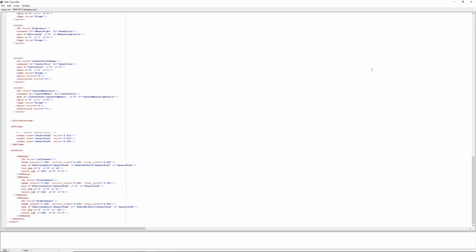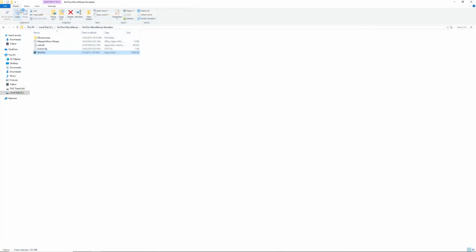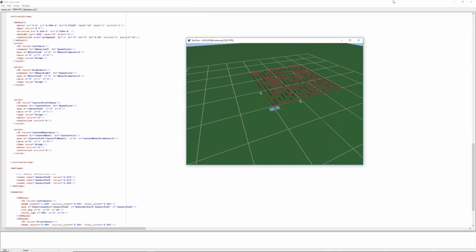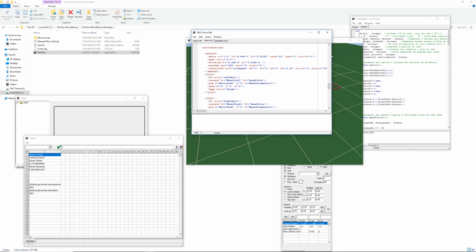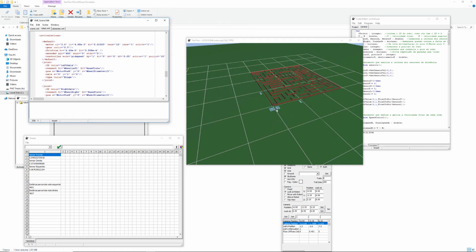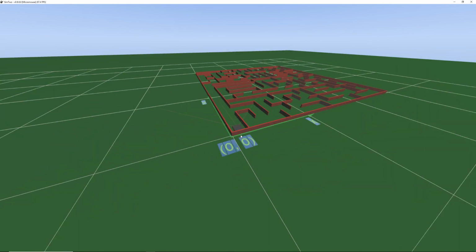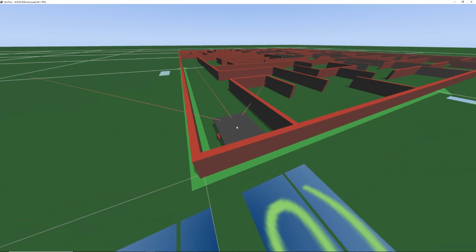To bring our robot to the initial position again, we go to Scene and hit Rebuild, Control B. Now this puts our robot back to the home position at the 0 position right here. So you can see that our robot now is not moving and is in a home position.